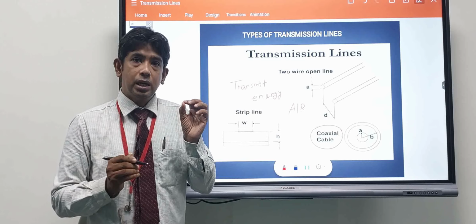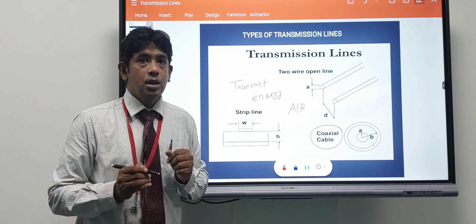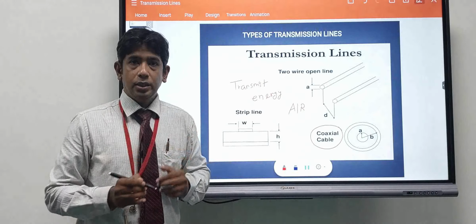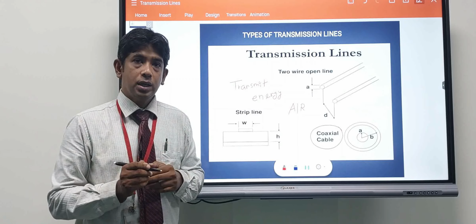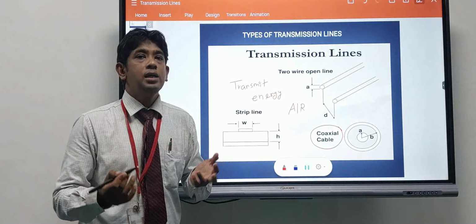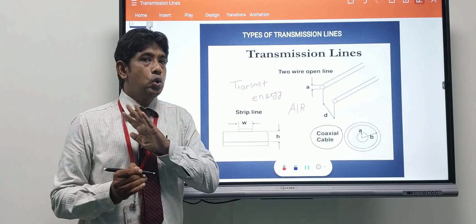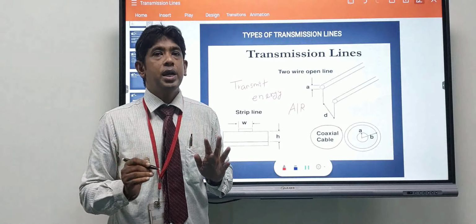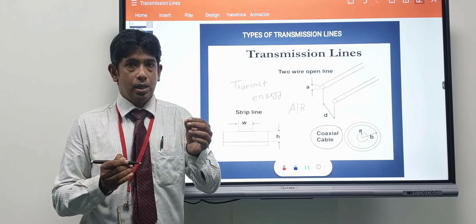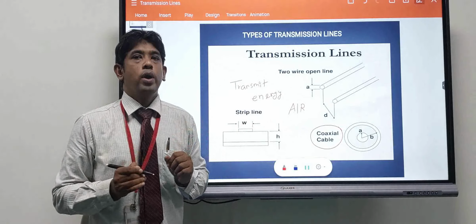Here the inner tube is separated and insulated from the outer conductor by a medium which may be solid or gaseous. The two conductors are at two different potentials. The fields are entirely confined to the space between the two conductors, and similarly no external radiation can penetrate the outer tube and propagate inside. Here the source is connected to the inner conductor of the coaxial line.